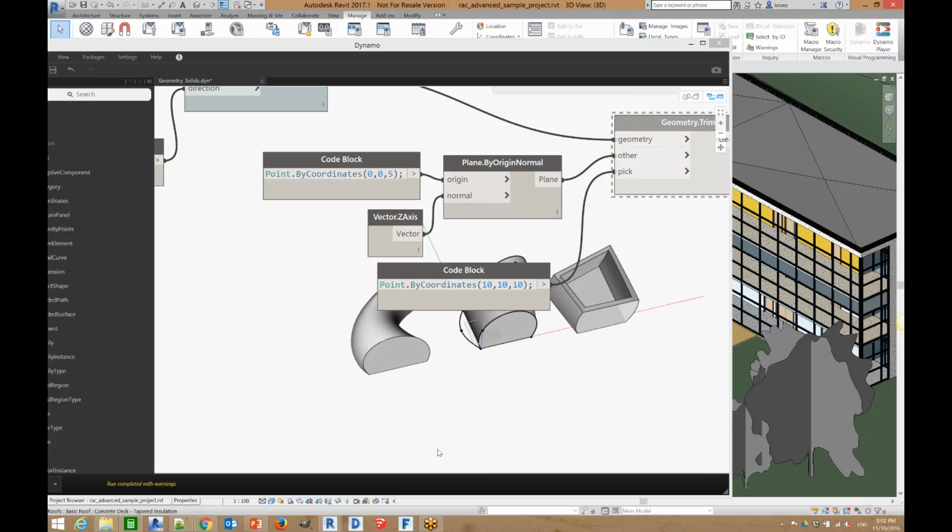You can open up multiple views of that same document and it'll still be operating on that document. It can repoint to whatever the active view is, for instance. There are different tools for monitoring specific views or your active view, but it will only point at that file that was active when you started Dynamo.